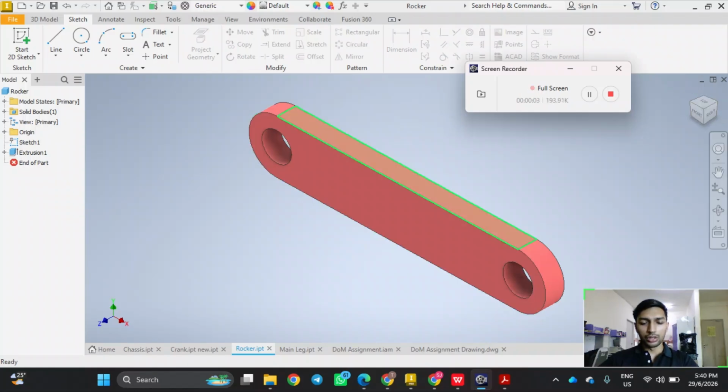The next part is the rocker, which is the red component, which acts as the follower link in our mechanism, modeled similarly to the crank but with an extended center to center hole distance. It is structurally constrained to oscillate back and forth. This oscillating motion is crucial because it controls the physical trajectory of the leg, enforcing the necessary lifting action during the recovery phase.